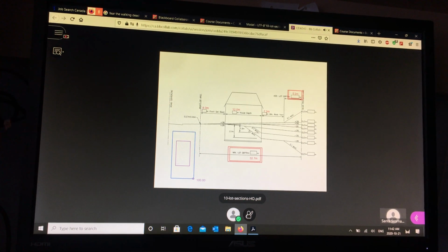Now the drawing is exaggerated a little bit. The distance from the front of the lot to the front of the building is 8 meters. Right? Let's put that in. This is 8 meters, going from here to here. The typical setback on the side yard is 0.6 or 1.2 meters, either 2 or 4 feet. It's relatively short compared to 8 meters, so keep that in mind. We're going to do a very crude calculation.